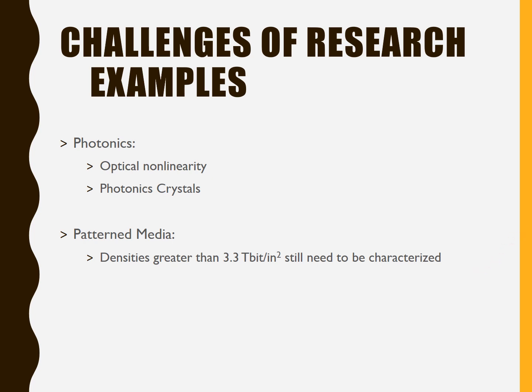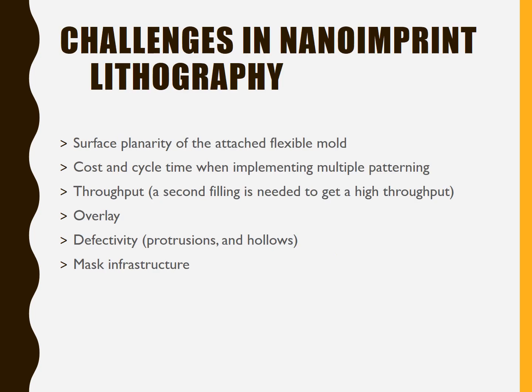All right. So some challenges of nanoimprint lithography: surface planarity of the attached flexible mold, cost and cycle time when implementing multiple patterning, and throughput. Throughput is interesting because it's also one of its advantages over other lithography techniques, but here we're focusing on the need for a second filling to get a high throughput.